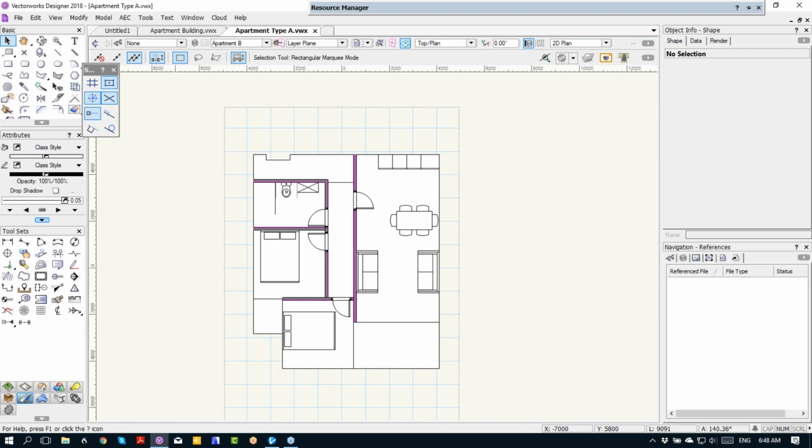So if I bring in a design layer viewport, sure, I have the ability to turn off the roof as a layer on that viewport. But if I've got 30 or 40 of those buildings, then I have to select all of them and turn them all off. Wouldn't it be easier to maybe have the roof on a class and turn the class off?